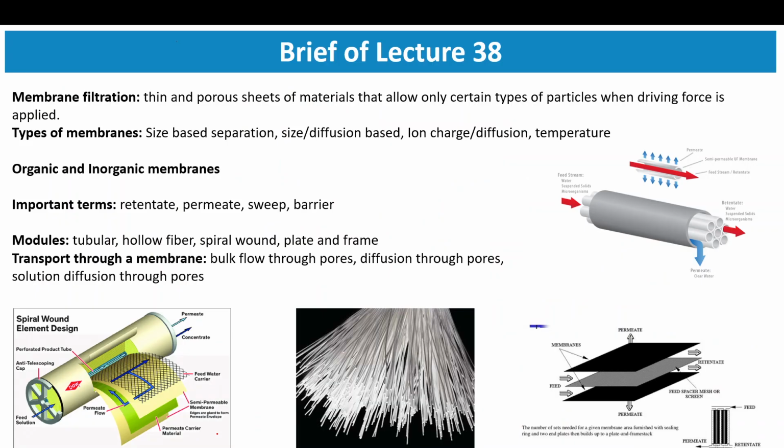Now, moving forward, another type of tertiary treatment which is discussed is nothing but membrane filtration. So, membrane, as I have mentioned or given you some brief, is nothing but a porous or thin sheet which has the tendency to allow only certain type of materials through it, and it retains some type of material. So depending on different characteristics of materials which are present in the wastewater stream, it will be able to pass some amount and it will be able to reject few types of material.